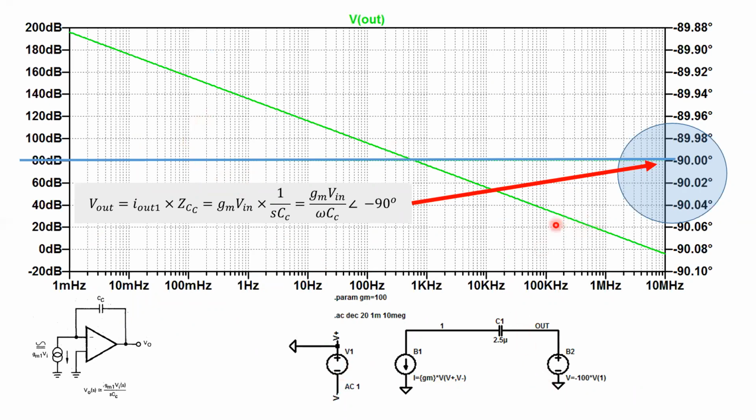And notice, I have this straight line coming down, so that's some open loop gain divided by S. That's what an integrator looks like, right? But what's the phase of a pure integrator? Well, there's no real part, right? It's all imaginary because S equals j omega. So the phase is a constant minus 90, which I've highlighted in blue so that you can actually see it.